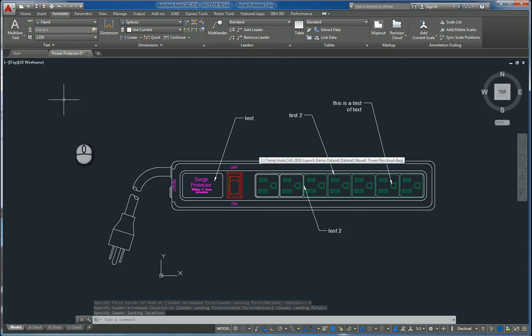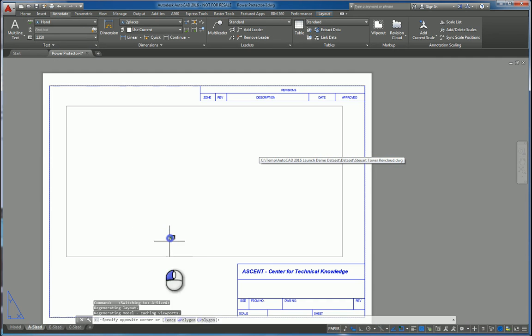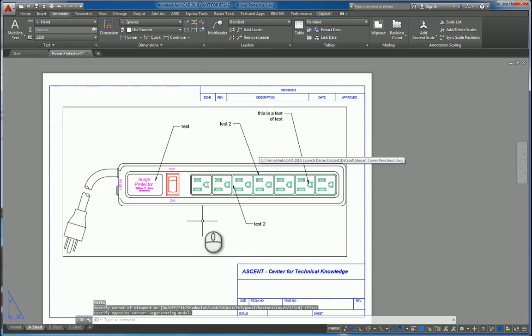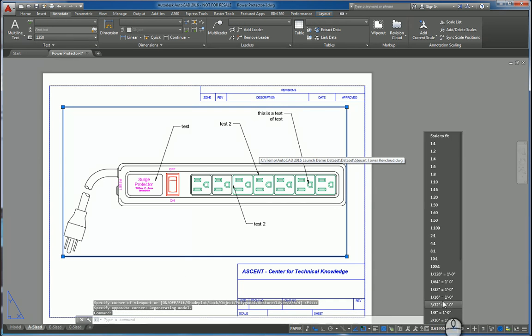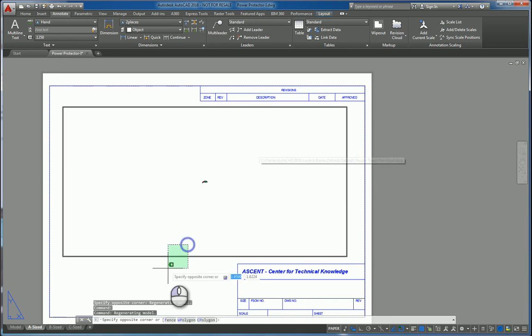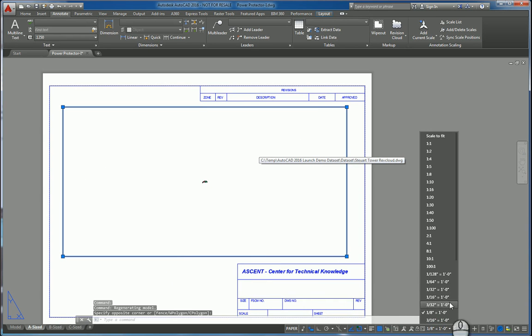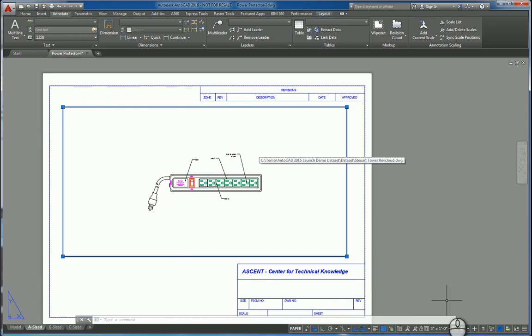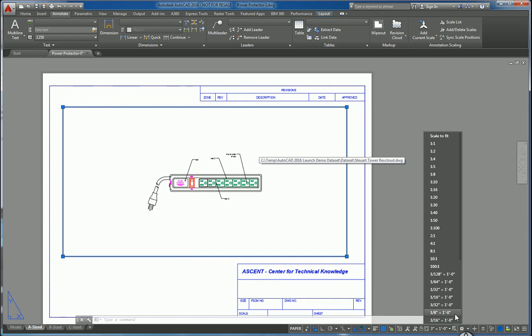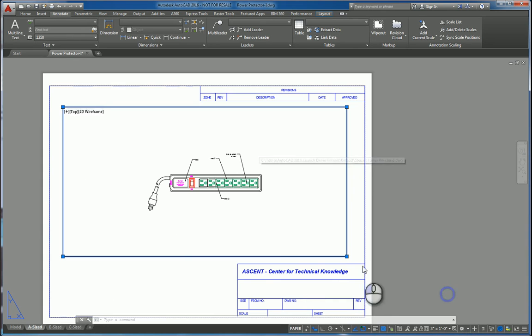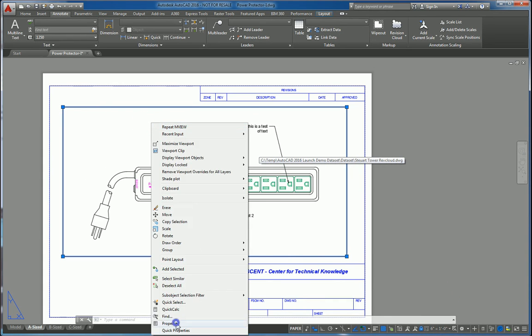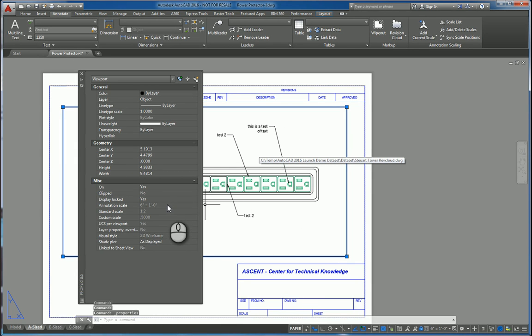If you're working with, let's head over to paper space. Let's delete this. Let's create a viewport. And let's go into this viewport and we'll set the scale to 1/8 inch. Nope, too small. Let's set it to, scroll that down. Say 3 inches equal to a foot. And let's go 6 inches equal to a foot. All right, and then we'll lock it so it doesn't get messed up. And if we go to the properties just to double check, the annotation scale should be the same by default.